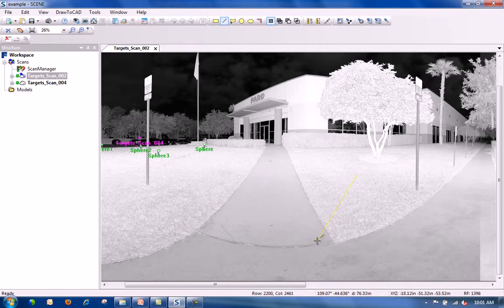There are points selected here, but they're only the very few points that are directly under this line. You can also make it a longer line by left clicking, left click, left click, left click, double click to keep that. Or I can left click, and if I don't like it, I can right click it to get out of that command.